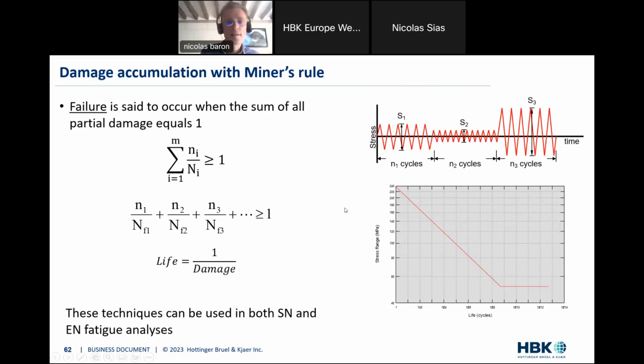So there are two results in terms of fatigue. When you express your results in terms of fatigue, you have two ways mainly to express your result. First, you could give a number, the so-called damage value. It could be a very small number, it could be 0.001, for example. That's the damage value. And the second way of expressing your results will be in terms of life. And the life, which is 1 over the damage value, is the number of repetitions of your input cycle.